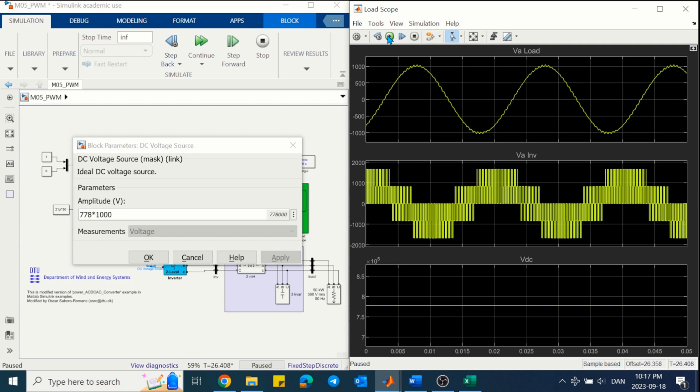So the value of the DC link voltage is reflected on the AC side. If we change the DC link voltage, we are actually scaling the AC voltage in the same manner. That is why we see the output voltage increasing without any limit, despite the fact that we introduced the saturation on the modulation index.